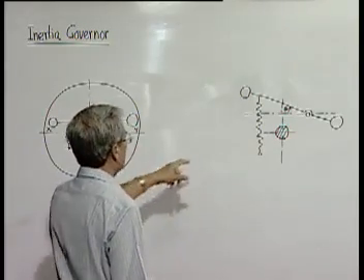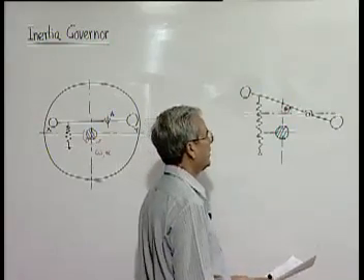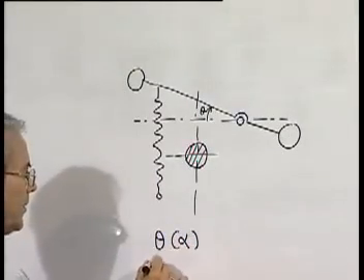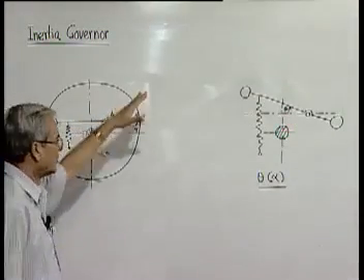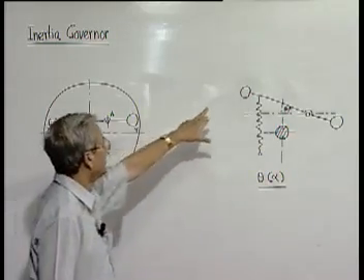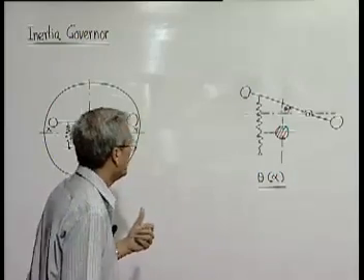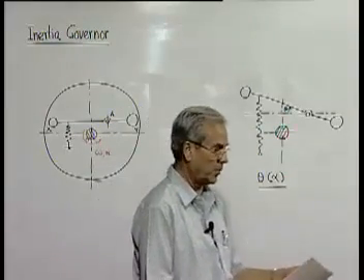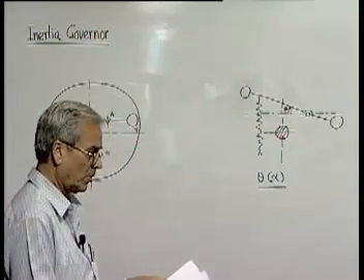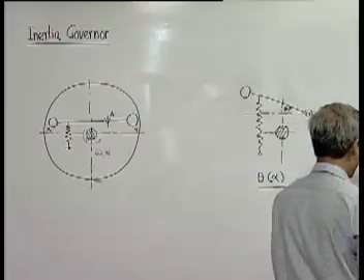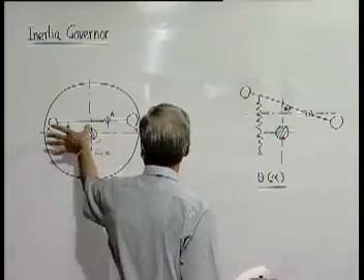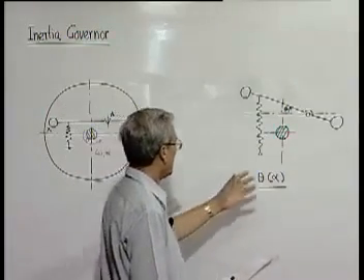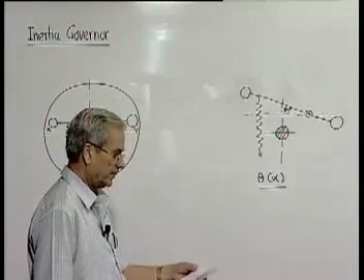Here we will not go into the derivation, but you can definitely try to find out what the relationship will be between theta and alpha, theta being a function of alpha. The moment it tries to accelerate, as soon as the load changes, immediately it will come back to a position. It does not have to wait till the speed changes to some suitable value and then sense it. So, it is definitely much quicker in response. This type of governor is called an inertia governor or sometimes a flywheel governor. I think this will be an interesting exercise: you assign various dimensions and then find an expression of this angle of rotation in terms of alpha.